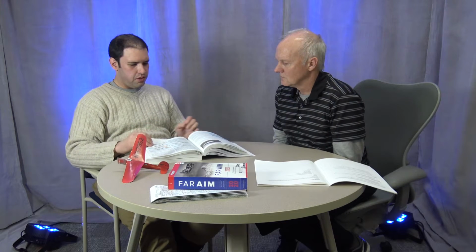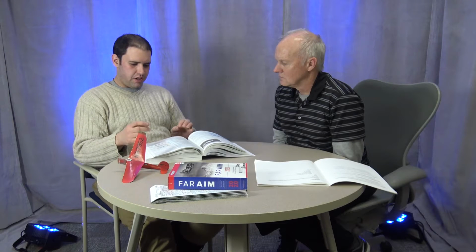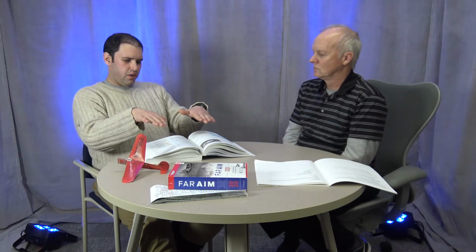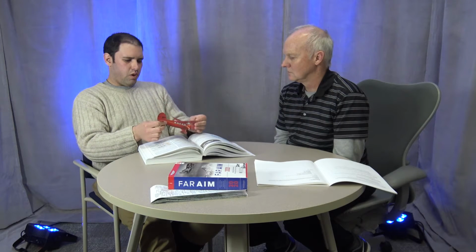Then you get into flaps, which are usually inboard of the ailerons towards the fuselage, and those come down together. And we talked about how when the aileron goes down, that increases the average angle of attack of that wing. Well, the same thing happens with flaps. As flaps go down, it increases the average angle of attack of the wing.